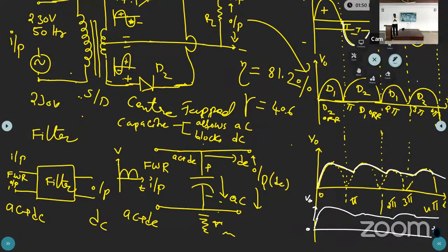So first the rectifier converts the pulses in both directions, that is bidirectional, to unidirectional. That is the pulsating DC. After the pulsating DC, connect the filter. That filter removes the AC part, leaving the DC. Now after the DC, we can connect the regulator. That regulator will give our required output for the mobile phone or any other electronic gadgets.